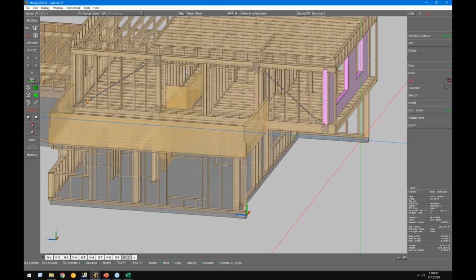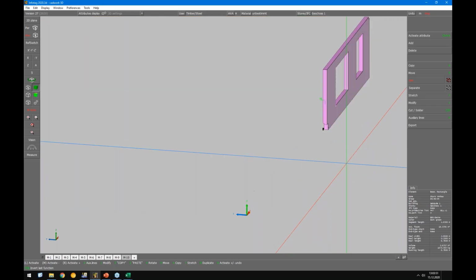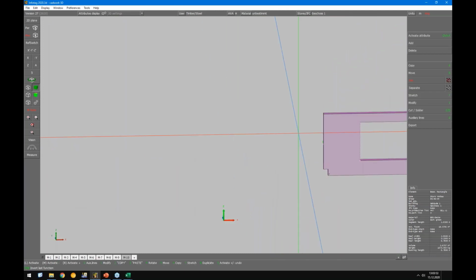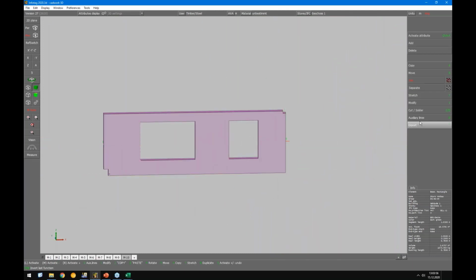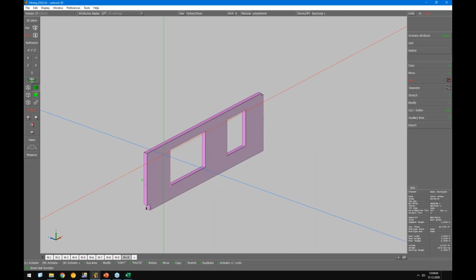The aim now is RFEM, and we can use it by exporting, for example, an IFC file, or we can export a DXF file, for example. But there's one smarter solution. In this case, I will have a look only at this element here, and I'm interested in the center lines actually, because this is a solid element, and of course I want to design it with a surface element and not with a solid element. So therefore we need the center lines.